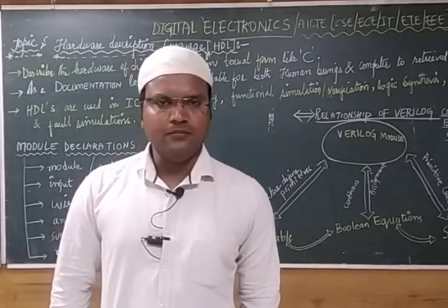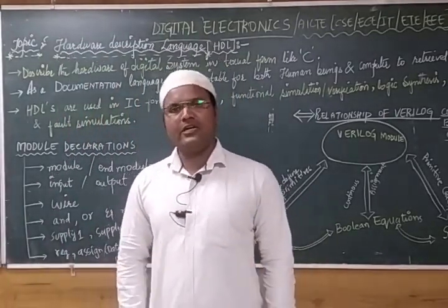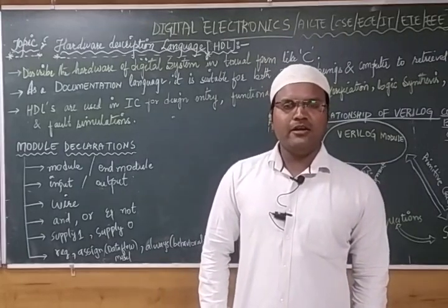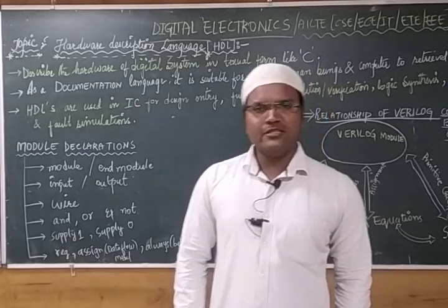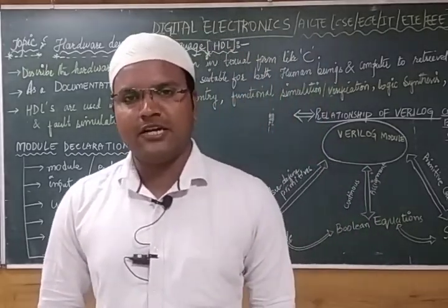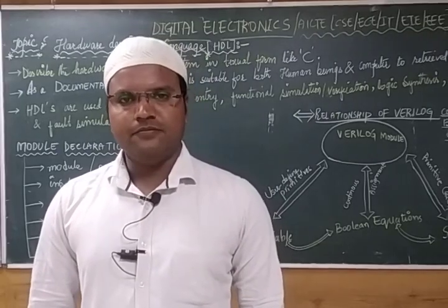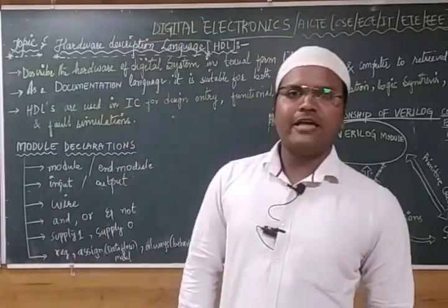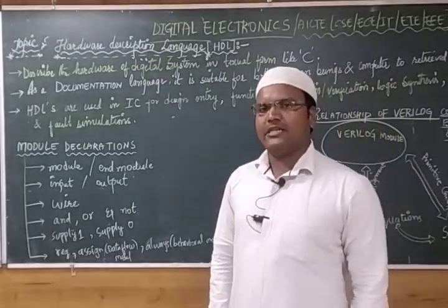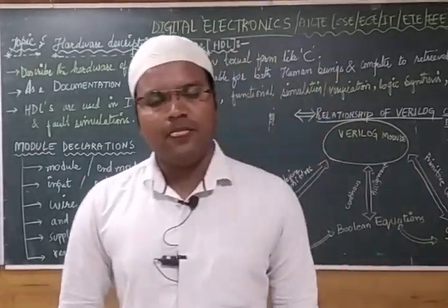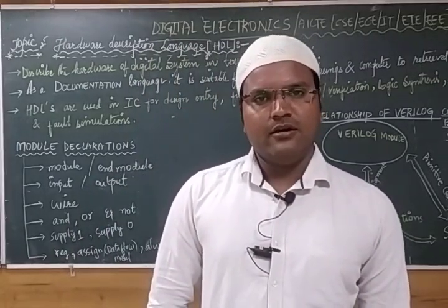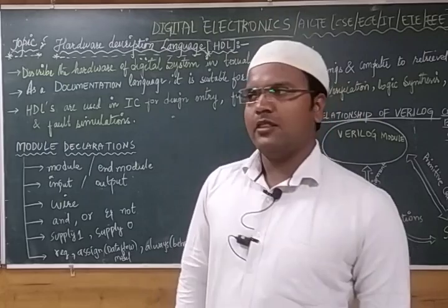For the SR flip-flop, we did it by using the NOR gate and NAND gate. The NOR gate is active high, and the NAND gate is active low. For the NAND gate, when S equals 0, that is called the set condition, and when R equals 0, that is called the reset condition. For the NOR gate, it is active high. Active high means when S equals 1, that is called the set condition, and when R equals 1, that is considered the reset condition. So we have discussed those concepts using the NOR gate latch.